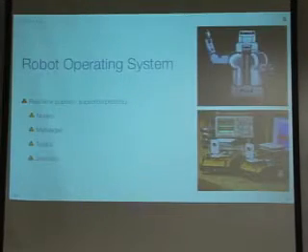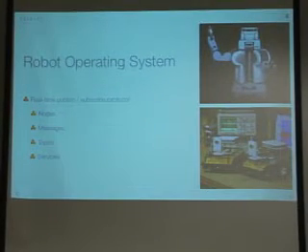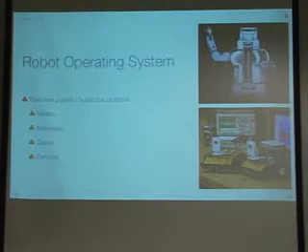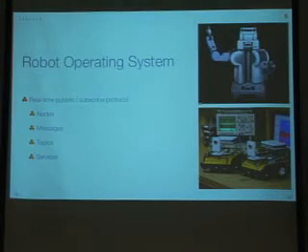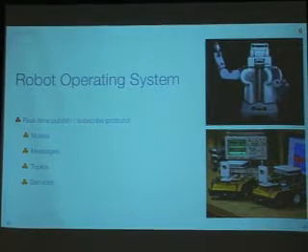For the robot itself, we are running Robot Operating System, which is also called ROS. Unlike a traditional OS, ROS runs on a publisher-subscriber model. It has software modules called nodes that, instead of outputting data, publish this data to a certain topic. Other nodes can then subscribe to that topic and take data from it. This is an asynchronous way of transmitting data. There's also something called a service, which is the way you can synchronously get this data.